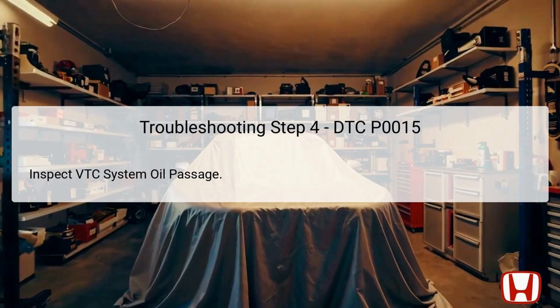Begin the inspection by checking the oil passage for any visible signs of blockage or contamination. If necessary, use pressurized air or cleaning solvents to clear any potential obstructions for better flow. Any detected issues should be rectified, as maintaining clear oil passageways is crucial for optimal performance in the VTC system. Documenting the condition of this system is important, as it provides critical information for resolving the DTC.